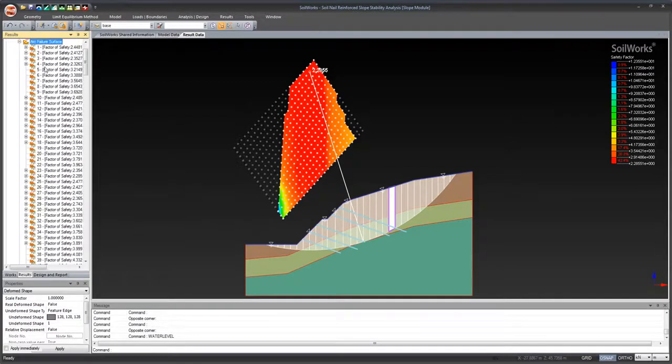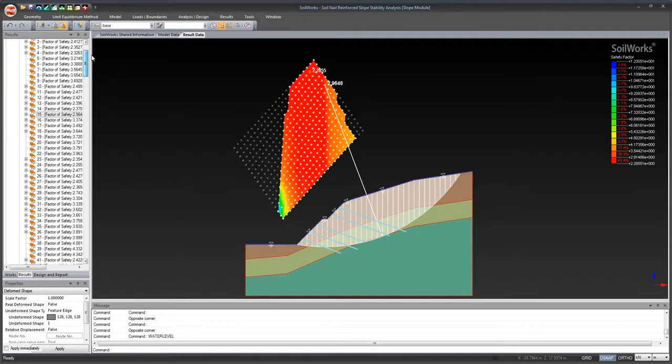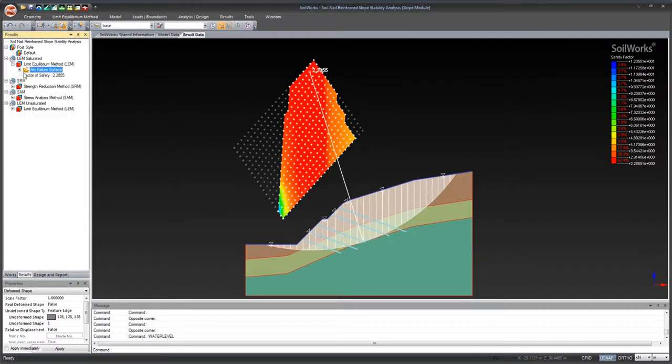And then if you open up this tab here, as you can see, the program did the factor of safety calculations for each of these failure surfaces. Let's see how many exactly. Yeah, so it did about 298 iterations, all within a matter of seconds. I know with LEM, the analysis itself takes less than a minute. That's something really beneficial about these software programs, or about numerical modeling in general: you can get a very wide range of analysis results that previously would have taken many hours for a single engineer to do. So that's very useful about it.